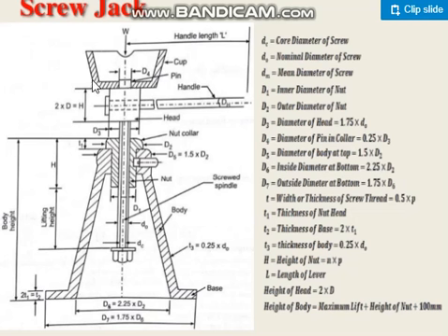On the cup only we will be putting the weight, suppose you are lifting a truck, so the truck weight will be there. Now what is the use of this cup? Suppose you are rotating this, and if this cup is not there, and the truck is directly sitting on this head, the entire truck would also rotate if the head is rotating.